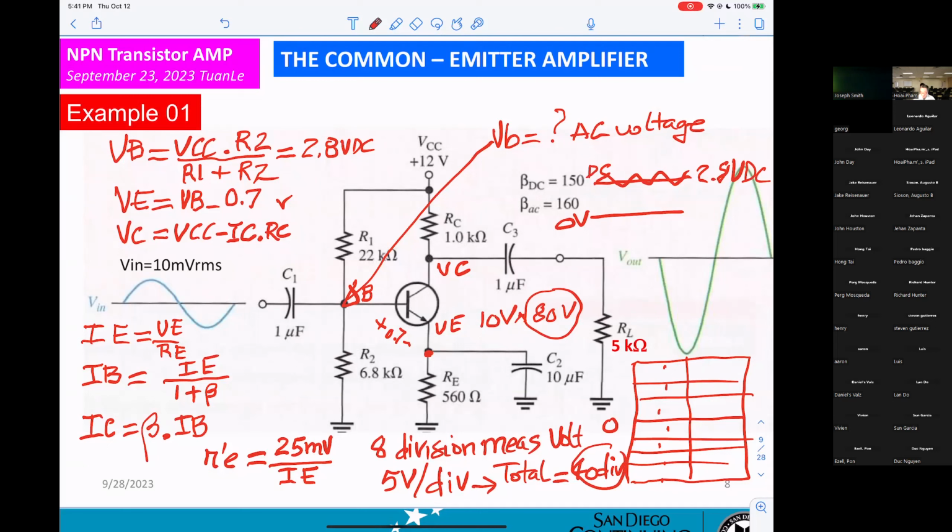That is why I'm telling you, when you do your lab volt, they're telling you to set the scope to by 10. You don't have to. If you know how to use the scope, we don't care about that. Any voltage less than 40 volts, you can set to by 1. Only when the voltage is too big, then you have to set it by 10.